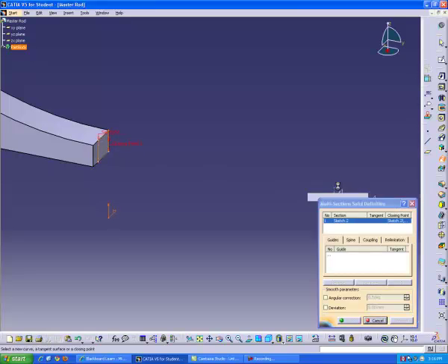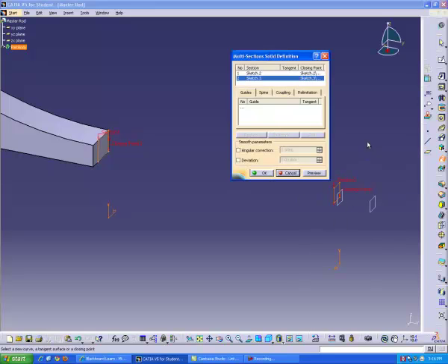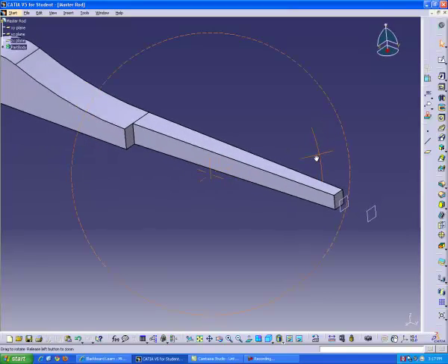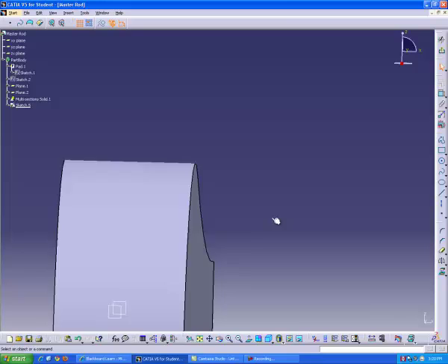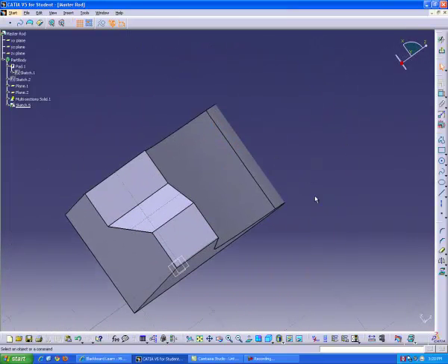Alright, here we're going to start lofting. I'm slowing it down because this part's kind of tricky. Basically you click the loft command and then you're going to click on the two sketches that you just made. Where it gets important is where the arrows are pointing, where it says closing point in section 1 and then closing point 2 in section 2. You got to make sure that those are one in the same place and two pointing in the same direction. So we had to reverse that one so it's pointing in the same direction, and now the loft looks good. We're going to do it again on the second loft. We'll make our sketch in here.